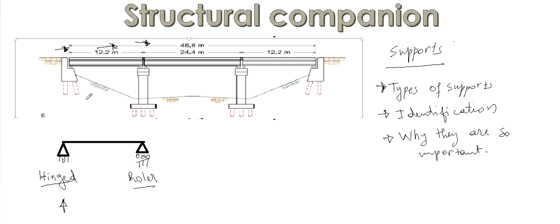The vertical reaction comes from all the loads applied on the bridge vertically like this, the loads coming from the cars and trucks. You need to determine this reaction based on the applied load, which I'll call W. In the hinge there is also another reaction, a horizontal reaction like this, that you need to determine.